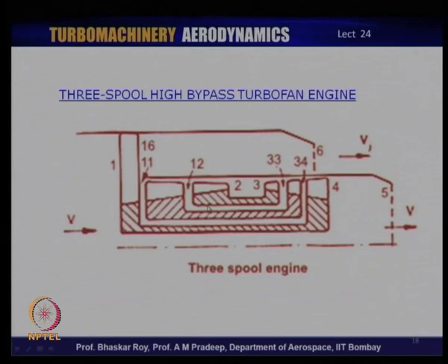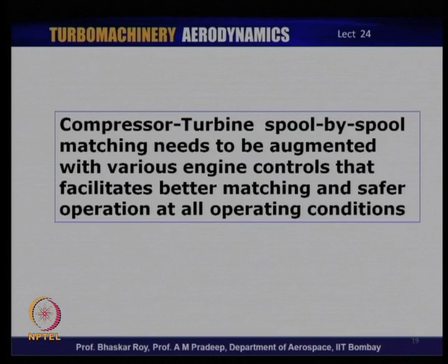So, this is how the 3-spool configuration is typically made, and we saw a 3-spool engine a little earlier, a picture of which indeed is based on this kind of spooling. So, we can say that the compressor turbine spool by spool matching needs to be done very meticulously, and this needs to be augmented in actual operation by various engine control systems. So, more spools you have, more complicated control systems you would need to create. And of course, mechanically you are making the system more and more complex. So, this is something which the engine designers would have to decide.